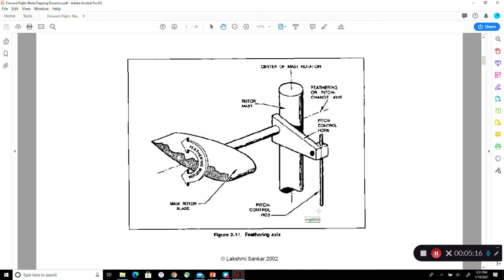Remember, dynamic stall is not a steady phenomenon. It goes in and out. The blade stalls on one side of the rotor disc, then attaches on the other side of the rotor disc. So this nose-down pitching moment will come and go once per rev. So this rod is going to get compressed, stretched, compressed, stretched. So it'll go through some fatigue cycle.